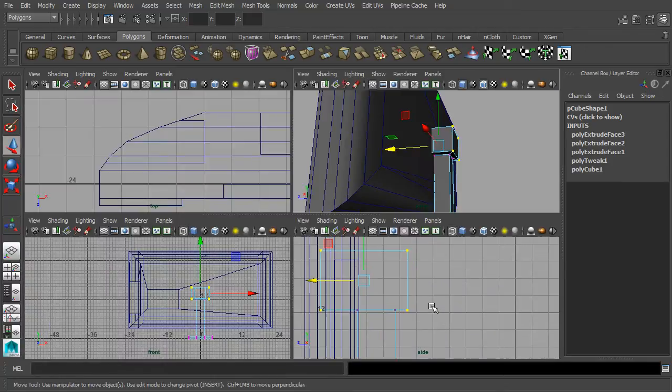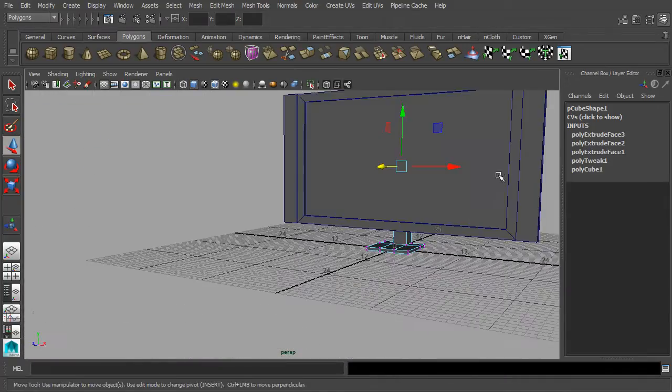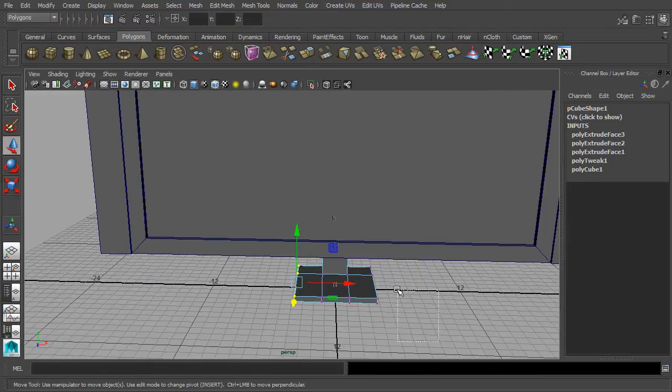Once again, check it in the side view. These vertices maybe don't need to be so deep in there. It's okay that there's an overlap here. We don't need to leave a gap. It's okay for that to project a little bit into there. Cool, so we can make our final adjustments to proportions, maybe by selecting these side vertices here. Control Shift, select, and I can scale as long as I'm careful. I'm scaling only in the X-axis here.